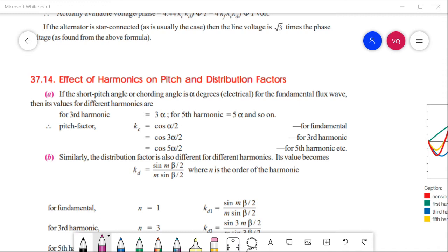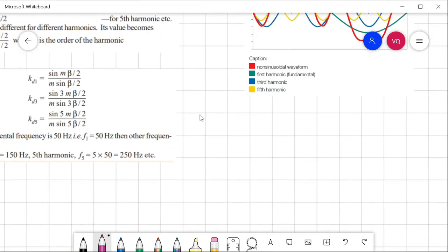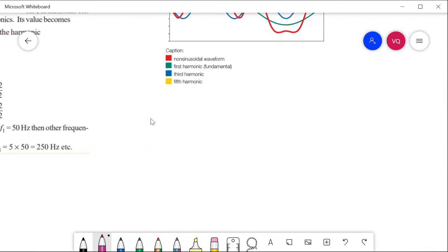Electrical degrees in a motor has to do with the magnetic position of the rotor. So one transition from north to south to north again equals 360 degrees. So for example, we have a two-pole, north and south. So north, south, south, north.